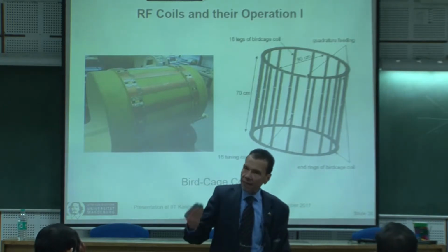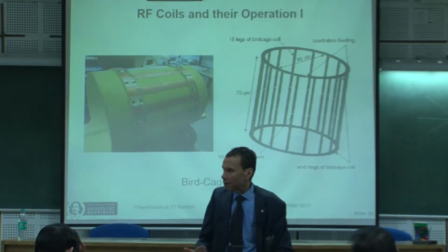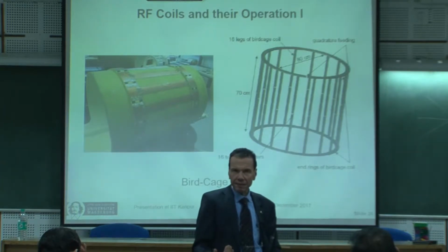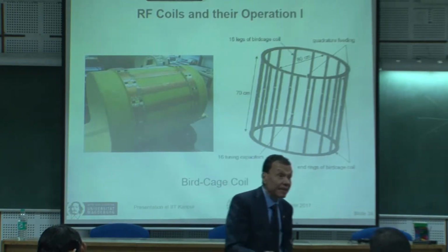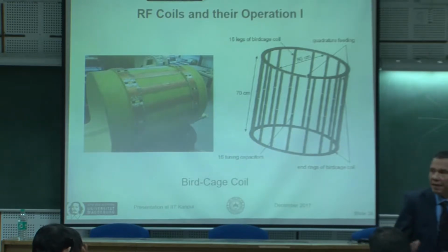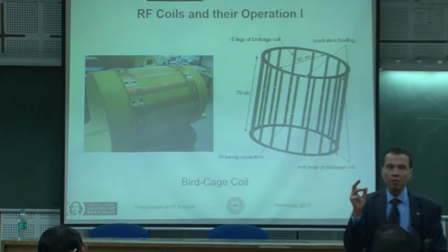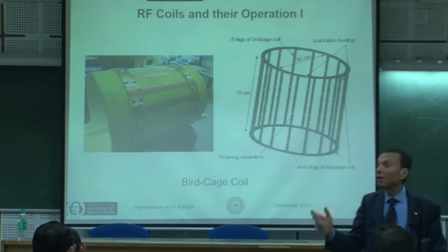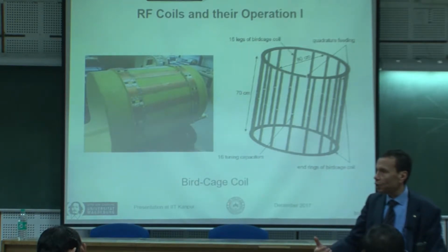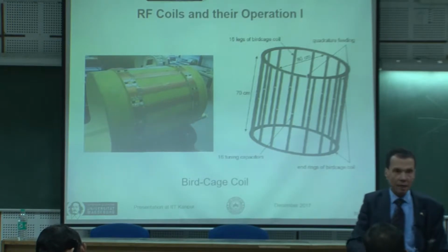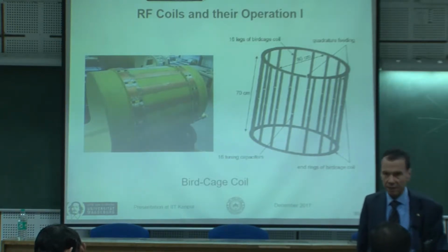Therefore, you should pay a little bit more attention in order to have a mechanism for purely circularly polarized, or at least, say, 80% in the proper circular direction and 20% in the other. These are all our design components and design factors and reasoning about what is better than what. This is now for the transmitting. So I would like to have as homogeneous as possible for the proper polarization and as much proper polarization as possible. If it is not there, it is not bad. You can image, but you pay with something, with more power or something like that.